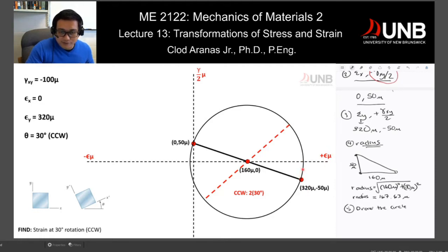That's the normal strain value. So if I rotate it by 60 degrees in Mohr circle at this point, I can take the value right here, and then I'll be able to obtain my epsilon y prime. Because this is epsilon y, and this rotation here from this point up to that point, that would be epsilon x prime. So now let's do it.